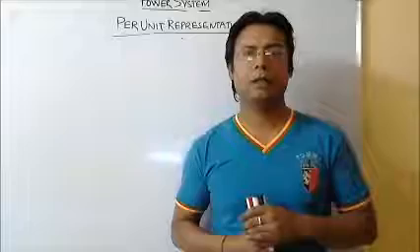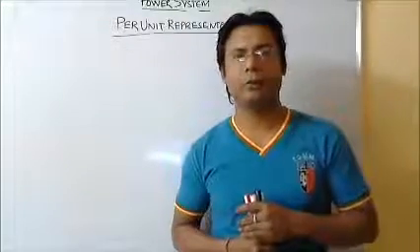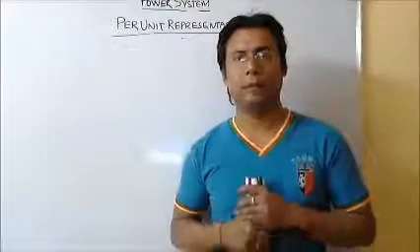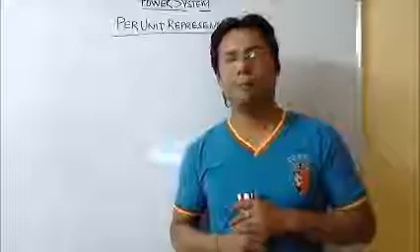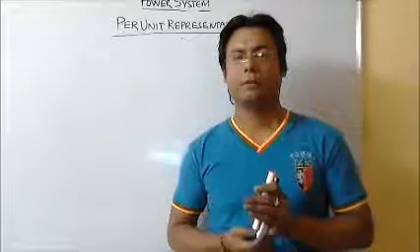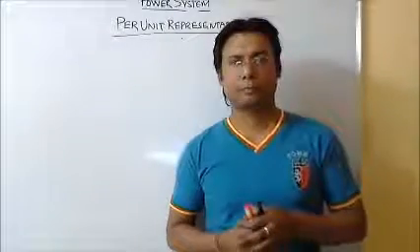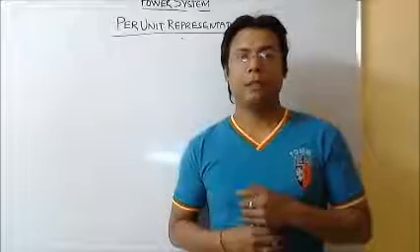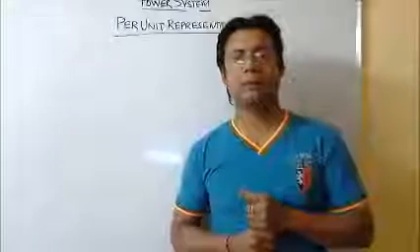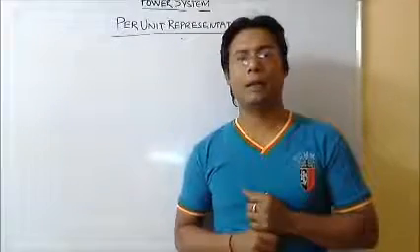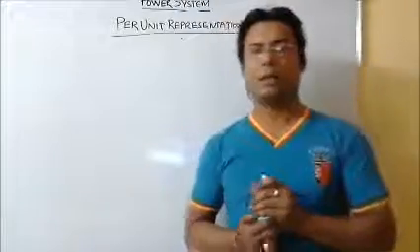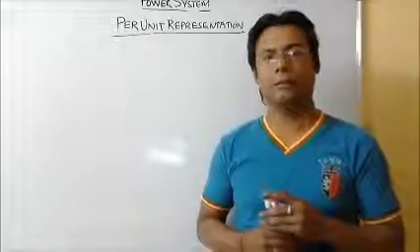In power system, sometimes it is very much necessary to determine the voltage, currents, and the kVA ratings all into a very convenient way of representation, that is called the per unit representation, in which the things which are actually on their base value are dimensionless, and they are easily computable by manual methods also. So we will be discussing the per unit representation.